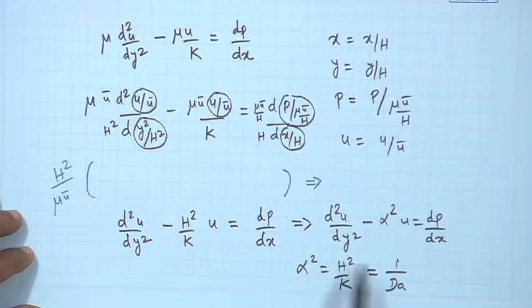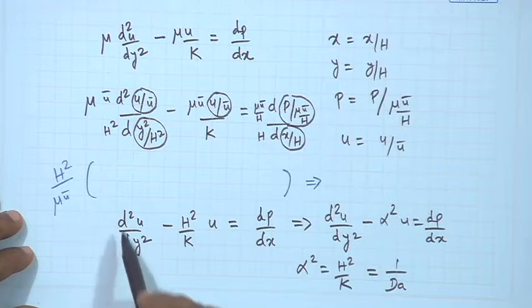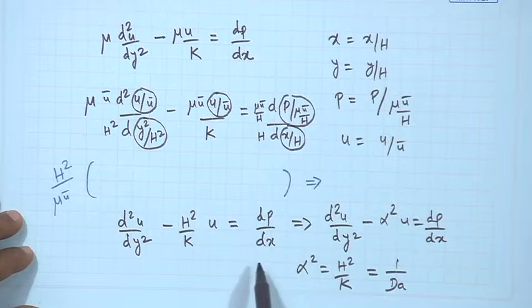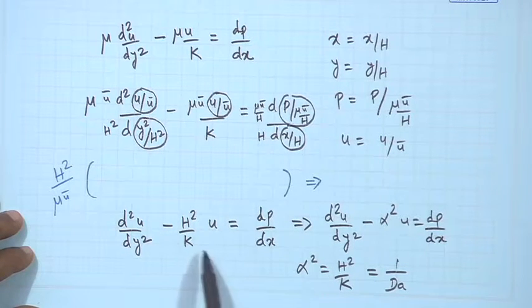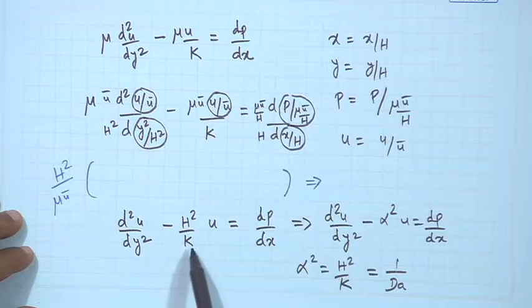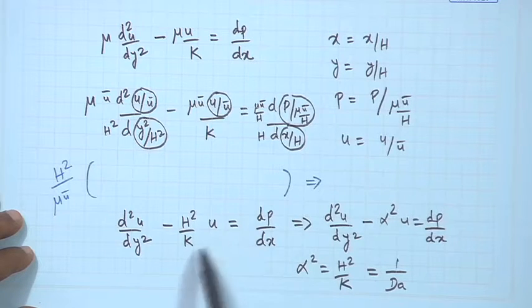So, the non-dimensionalization of the corresponding governing equation introduces a non-dimensional parameter, which we are defining as a Darcy number, or in this case 1 over Darcy number. If you see k goes to infinity, that will be producing a Stokes equation, the large permeability case. So, this is limiting.